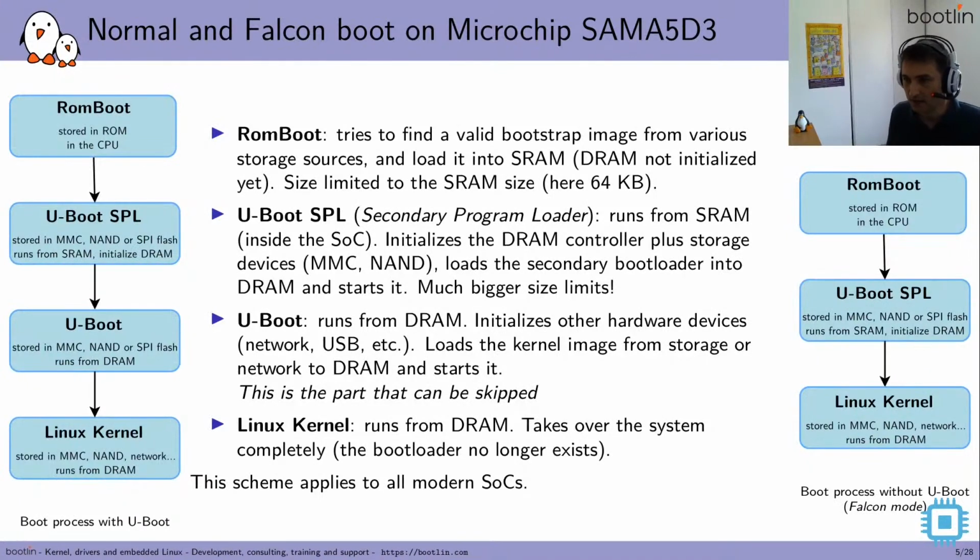Since the U-Boot SPL is actually loading U-Boot to DRAM, the idea behind Falcon Mode is to directly load the Linux kernel instead, also from storage to DRAM. So that's the same thing. We just skip U-Boot and hope to save some time.